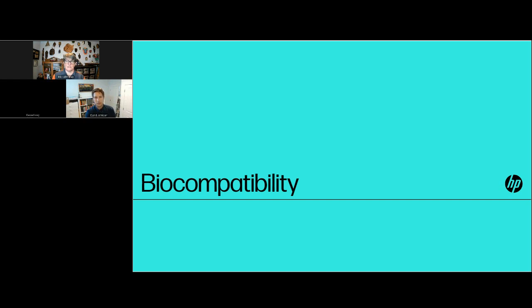For metal devices, they give you a bit of a loophole that they didn't actually put in the guidance document, lovely. It allows you to forego most of the biocompatibility testing if you have passivation as your final step involving chemical contact. The mistake a lot of people make is they do passivation and then a final clean prior to packaging. If you use, for example, Alconox for the final clean, they're going to want to know about the toxicity of Alconox, which, newsflash, is very toxic in itself, and they'll look at your cleaning validation to make sure you've removed all of the cleaning agents. So the best thing to do for metals is passivation as the final step.